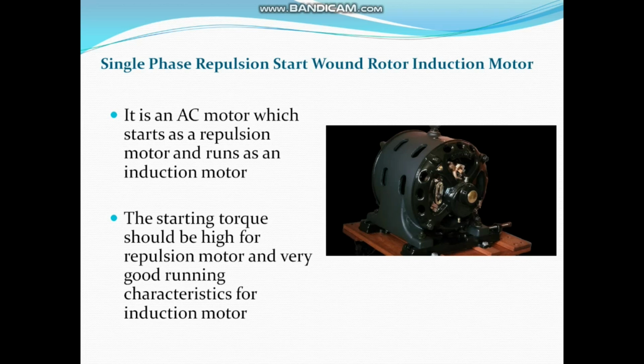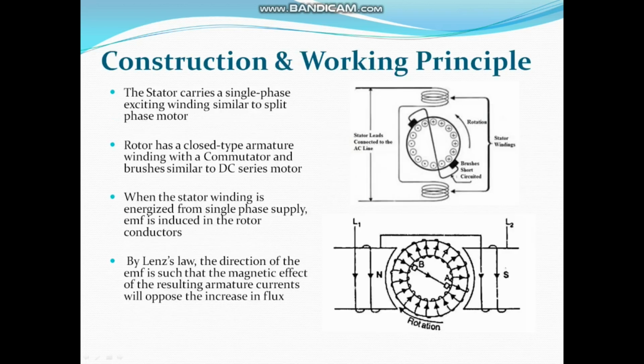Single-phase repulsion start wound rotor induction motor. It is an AC motor which starts as a repulsion motor and runs as an induction motor. The starting torque is high like the repulsion motor and it has very good running characteristics like the induction motor. Now, let's see the construction and the working principle.